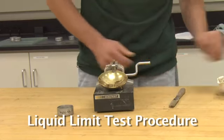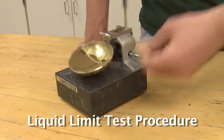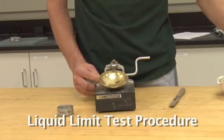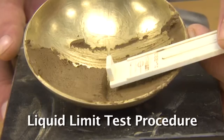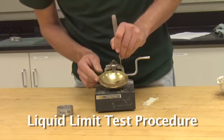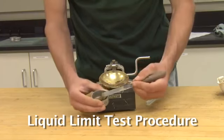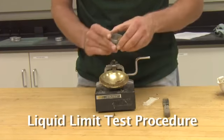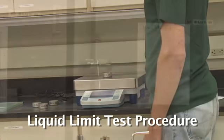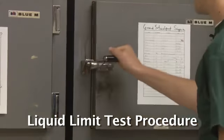Once the groove has been made, rotate the handle at 120 revolutions per minute, 2 cycles per second, and count the number of blows it takes to close the groove in the soil pat 13 millimeters or 1/2 inch, which is the width of the grooving tool handle. If the number of blows falls between 15 and 20, scoop out some of the soil and place it in one of the pre-weighed tare cans and record the new weight for moisture content determination.